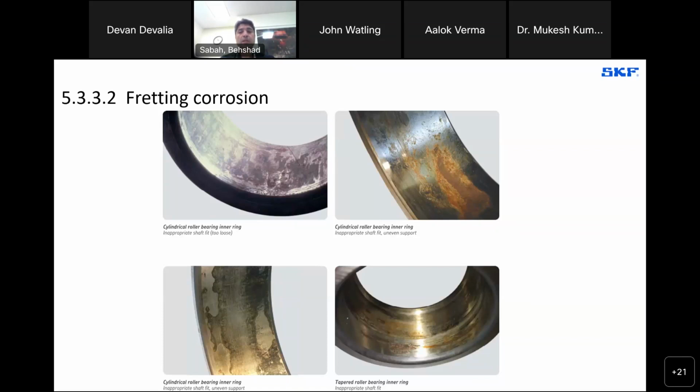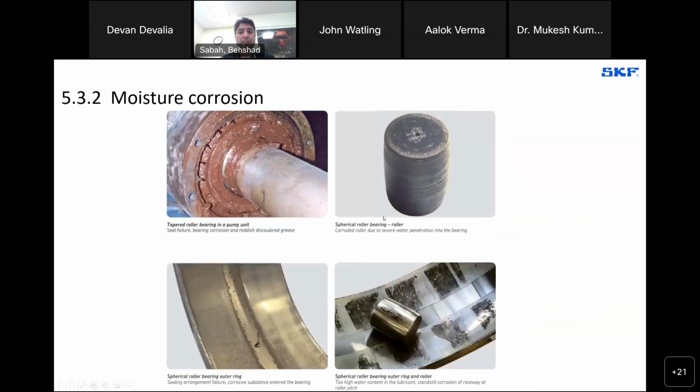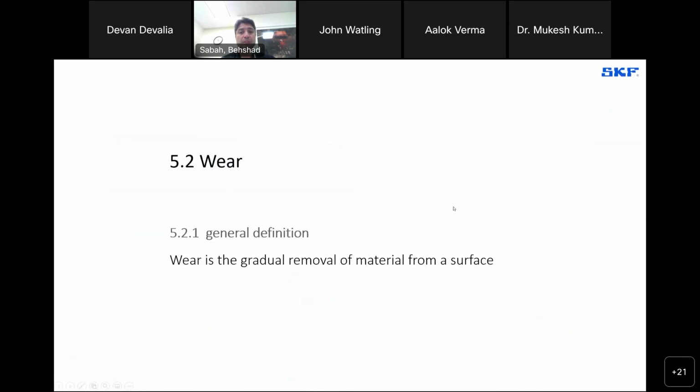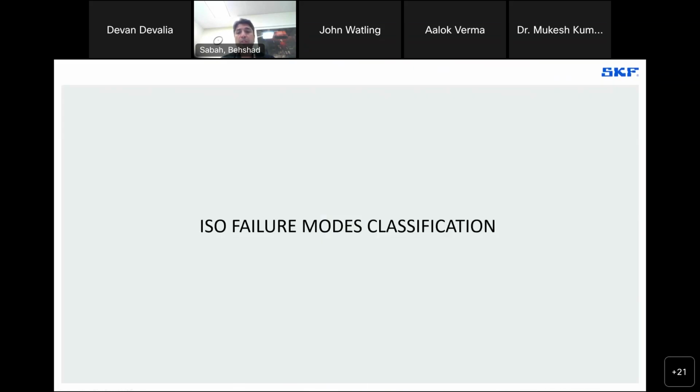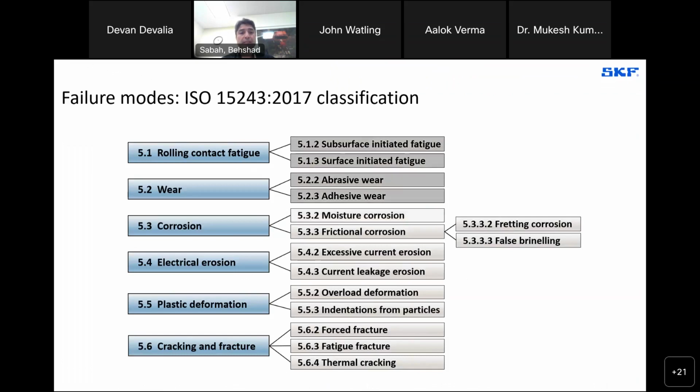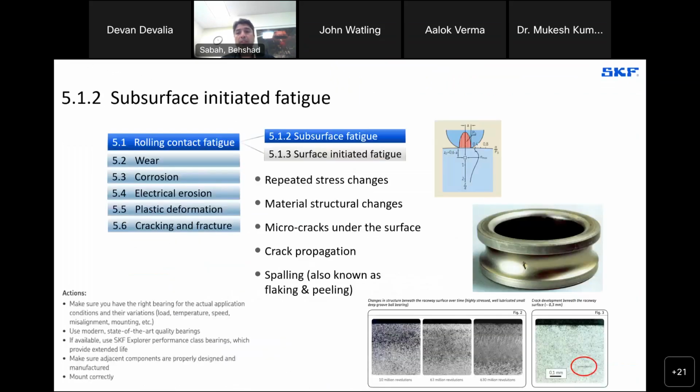So okay. Can you go back to the slide that you had about the subsurface fatigue, where you show that 630 million revolutions? There is a question here by John. He did a calculation that 630 million revolutions, at 3600 RPM, is equal to 122 days of operation.